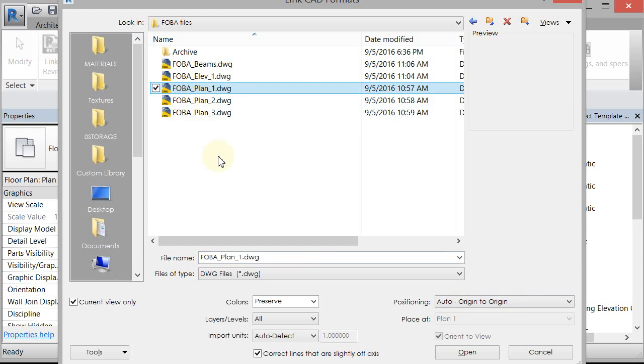And I would really recommend pre-planning that. Like if you're using Rhino, move the plan to the center where it's centered on 0,0, and then if you have a second floor, move the same center and export selected from that point. So you can just use auto origin to origin. You don't have to move them around.